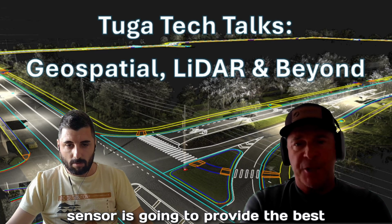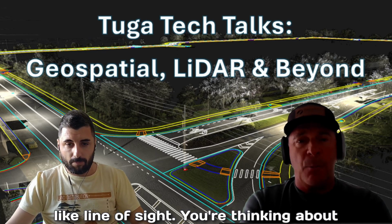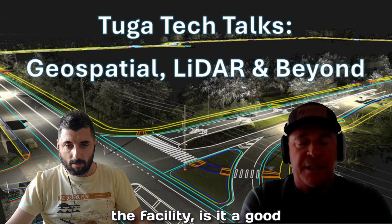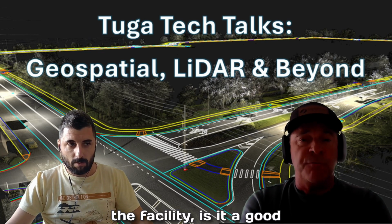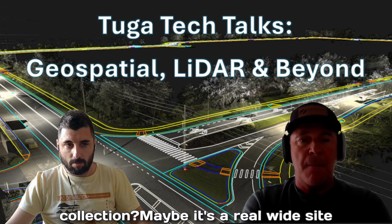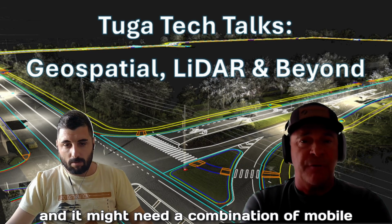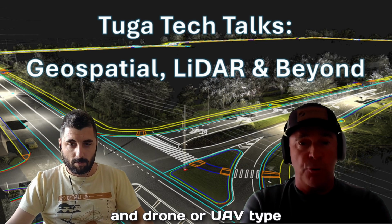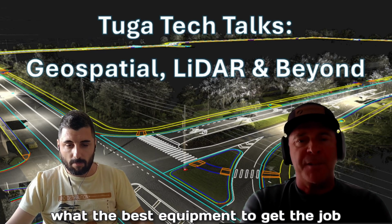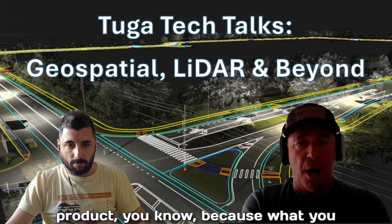is going to provide the best results. So you're thinking about things like line of sight. You're thinking about whether or not the facility is a good facility for a road mobile lidar type collection. Maybe it's a real wide site and it might need a combination of mobile and drone or UAV type system. So you're trying to figure out what the best equipment is to get the job done efficiently and provide a great product.